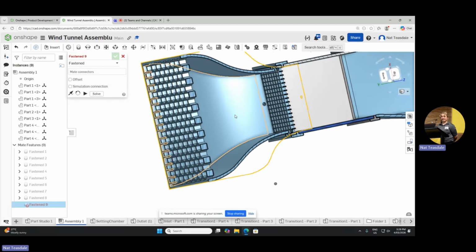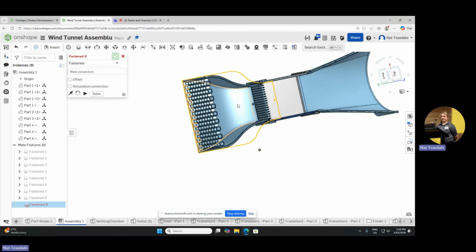But if we were to place this main settling chamber at the back of the inlet, what we would create is more turbulence and more vortices. This is because turbulence and vortices are accentuated when the airflow is faster. So our main settling chamber is placed at the beginning. We have a finer one down the end, which is just for any more keepsake stuff. Generally it just lets us make sure that our airflow is going to be neat. Otherwise, most of the airflow stuff is those two plus your fan.